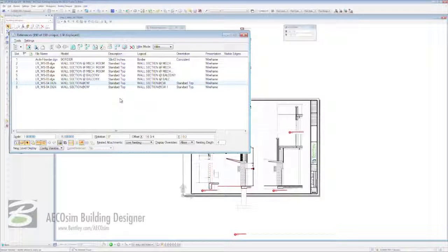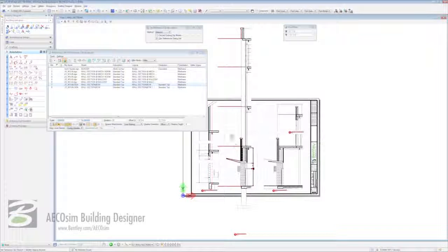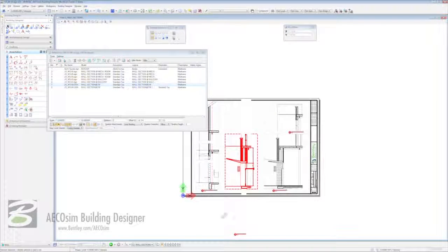I'm going to highlight my first curtain wall section, and I'm going to make it fit to that without disturbing the scale or any of the detail. I'm going to do that by clipping it. Third icon in my reference toolbar is clip reference. I've highlighted my reference. I'm going to select the clip reference, and then select this box around it. And straight away, I've clipped my reference.